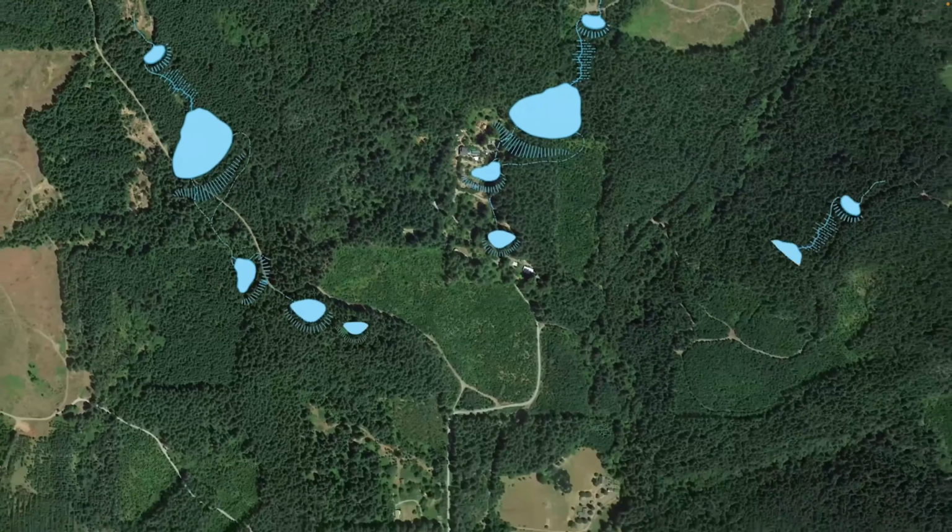A third type of dam, which really is not recommended and that I really try not to build. In theory, if you have enough clay, you can just build what's called a homogeneous dam, which is a dam completely constructed of clay, with the wall itself keyed into that trench at the bottom center of the dam. Still, it's always a good idea to really maximize the heaviest concentration of clay at the center of that dam to create that permanent seal.